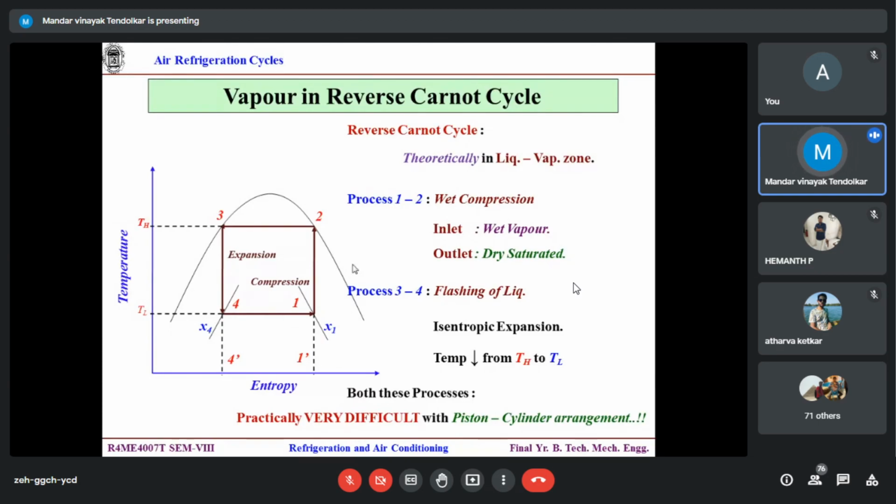So you require the motor only for the compression process and the expansion process. And there you maintain the speed as high as possible. So here you get rid of that practical difficulty of a two-speed motor, one at the lower and one at the higher speed. Only one motor is required at the higher speed, and for the low part, there is nothing required. It is a phase change process. So this is the only exception where you can execute a practical Carnot cycle. May not be 100%, as I said, but a 99% practical Carnot cycle in reality.